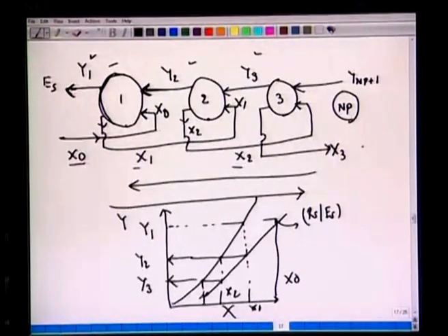Now it is also possible to treat this since two streams are entering concurrently, where we have x0 and y2. So x0, and we have this y2 here, and since it is co-current, we can draw the curve like this with the slope of minus Rs over Es. We have the same stage like this. Now it enters here, we can draw another stage, stage 2, and we can have stage 3.